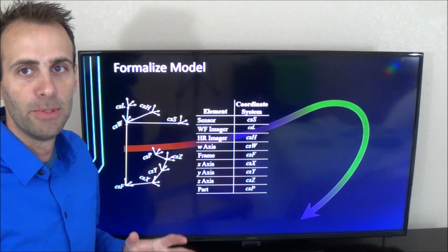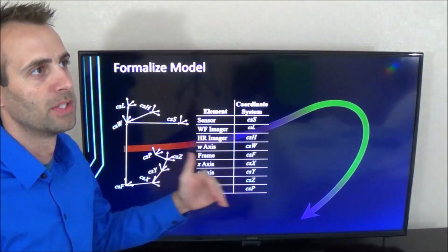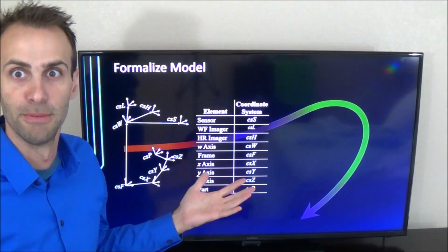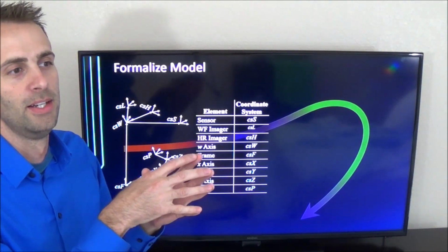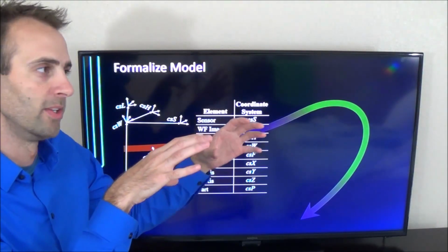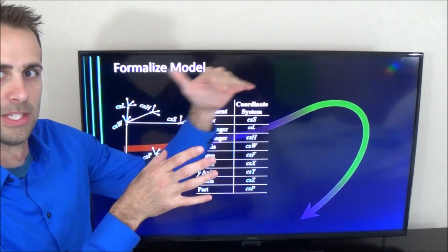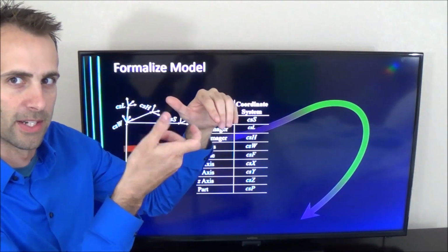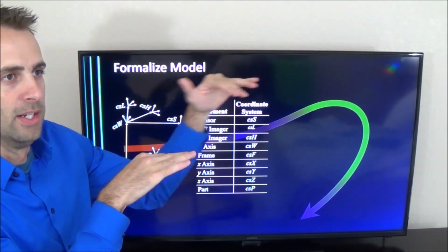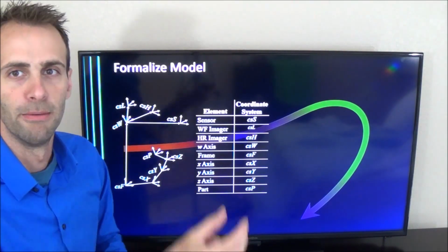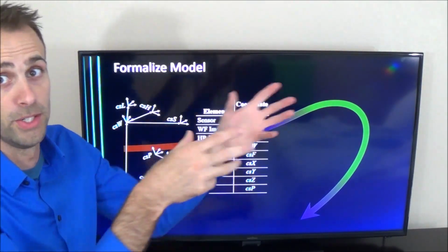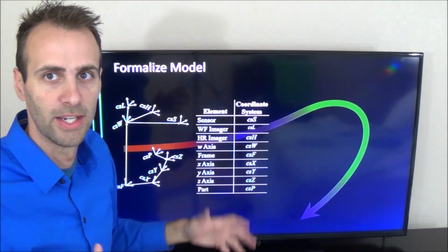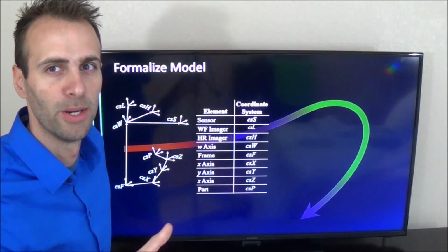Once you have the machine elements that you want to assign a coordinate system to, and typically it's one per axis at the minimum, and then maybe like on that knee mill, the quill is bolted to this thing that can slide, which would be parallel to the X, but it would be fixed. So if you wanted to put some little number in your software that, hey, if I change that, I need to remeasure where that position is, it's really simple. It's just changing one number.